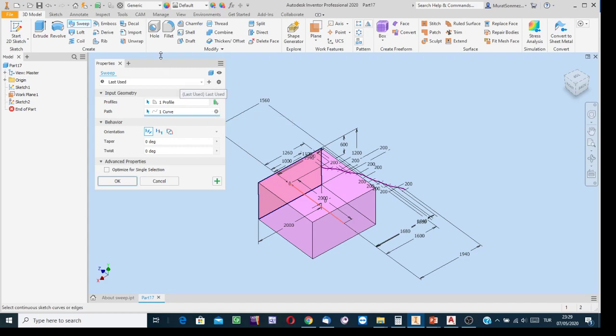As I said at the beginning of this classwork, to be able to create such a loft, the sweep process can be applied. But this is the trick. Select not this orientation, not that orientation, but the guide option. And this curved line is the guide.